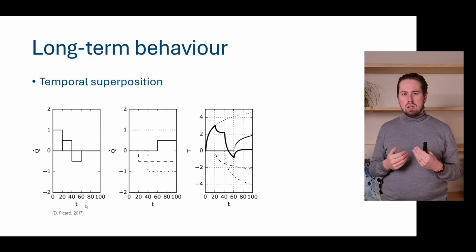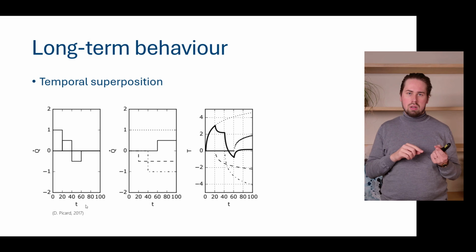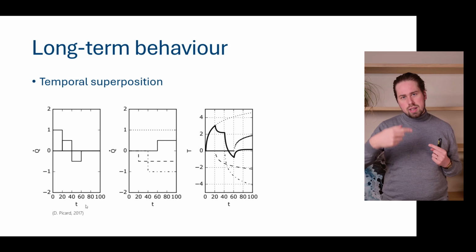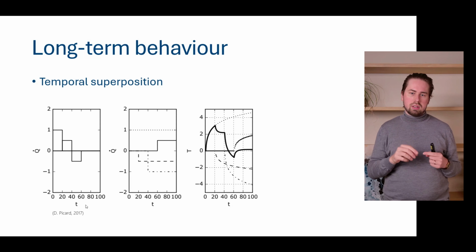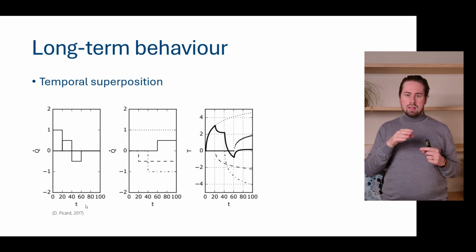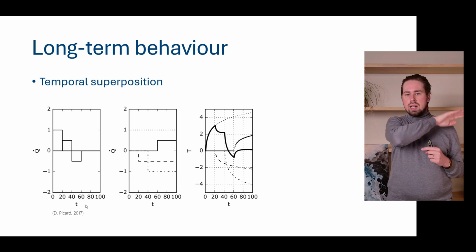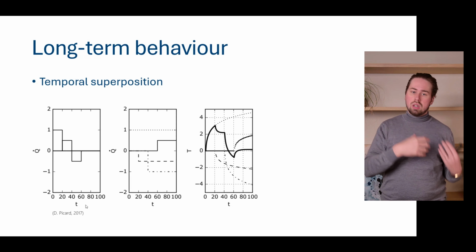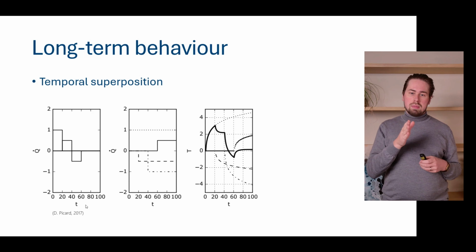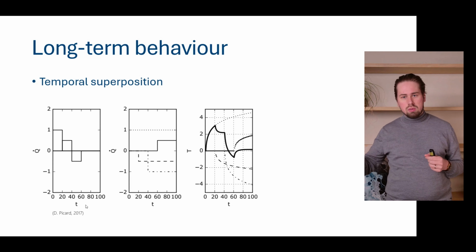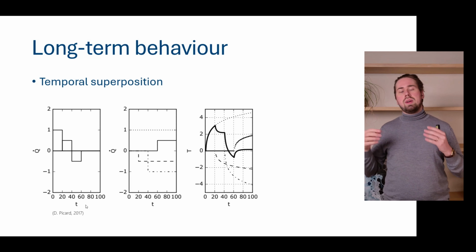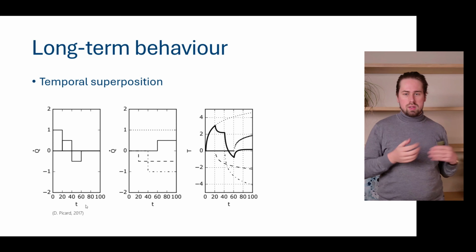For a load of minus a half, it's the same G function, but now negative and scaled by minus a half. And this we do for every constant load of the second figure. Then we end up with the graph on the right, where you see that at time step 0, there is this dotted line going up, which is the G function of our first constant load of 1 kilowatt. At time step 20, there is our striped line going down, which is our G function multiplied by minus a half. And then we have our G function multiplied by minus 1 and so forth.